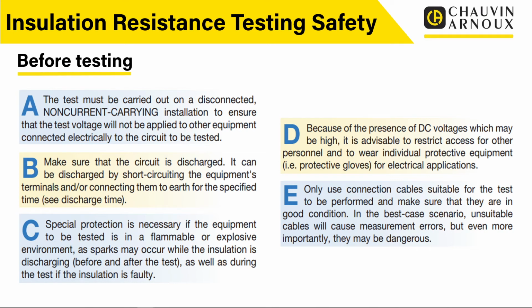D, because of the presence of DC voltages which may be high, it's advisable to restrict access for other personnel and to wear individual protective equipment, i.e. protective gloves, for electrical applications. So yeah, just think about your PPE in this case.